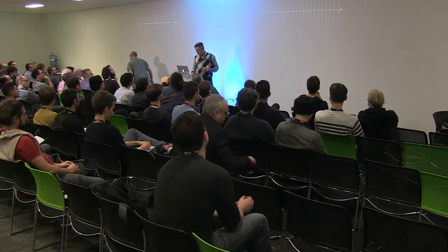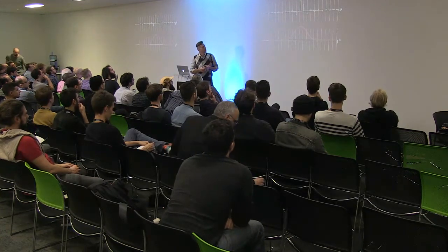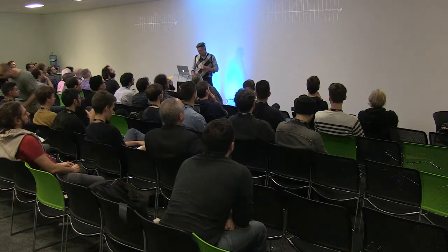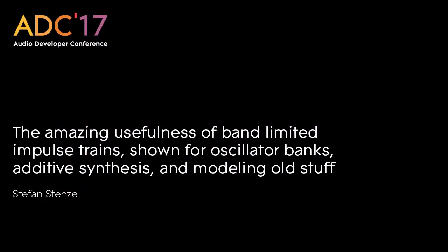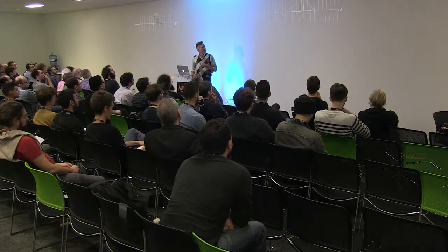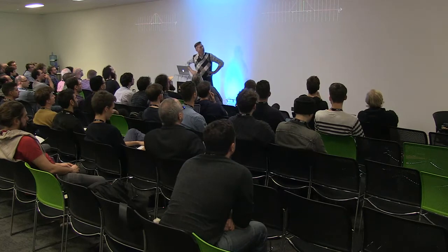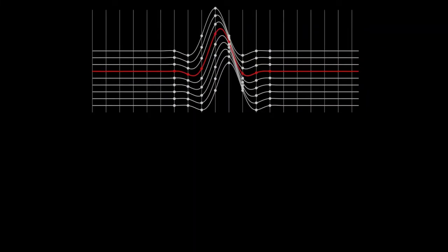So these are the discrete samples. We want it also locally in time, so we have a window function. We apply the window function, and we have it locally in time. This, of course, will introduce some errors. As you know, we can minimize that by dilating it a little bit, so making the pulse a little bit wider. It's still a sinc function, but widened a bit. We have several parameters for how we create sinc waves. What we usually do is create a bunch of those, pre-calculated, with fractional delays.